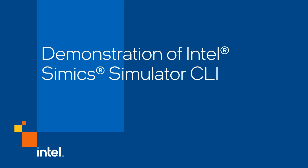The Intel Simics Simulator CLI is always available, regardless of how you start the Simics simulator. When the simulator is started along with the Simics graphic user interface, you can access the Intel Simics Simulator CLI from the Tools menu and then select Command Line Window. Now that you know the functionalities of the CLI, we will explore more of the simulator too. You will see that there are 3 windows open: the graphic interface, the Intel Simics CLI window, and the serial console for the targeted device being simulated.